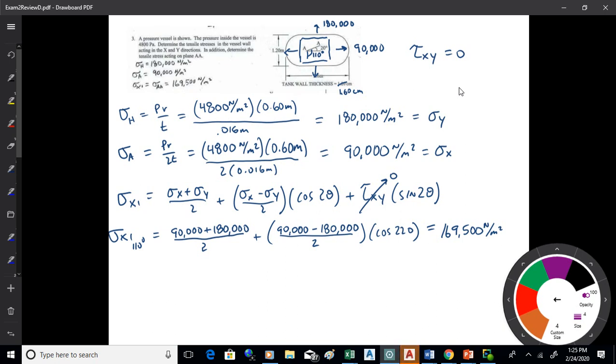Yeah, question? So for stress, again, it's off the vertical, right? Right, yes, and that's another thing. You're noticing I'm slipping that into the homework a lot because I want to be sure that you know that. And at some point on some test somewhere down the line, I'm going to put something in there to make sure that you know that you come off the vertical plane. I'll just tell you that because I want you to know that, okay? It's an important part of running these numbers. So just understand that. For stress, you measure counterclockwise off the vertical plane. That's the convention for that, okay?